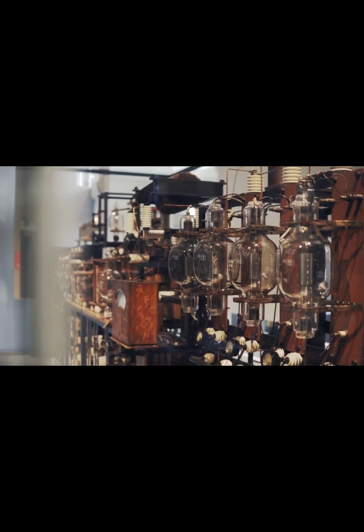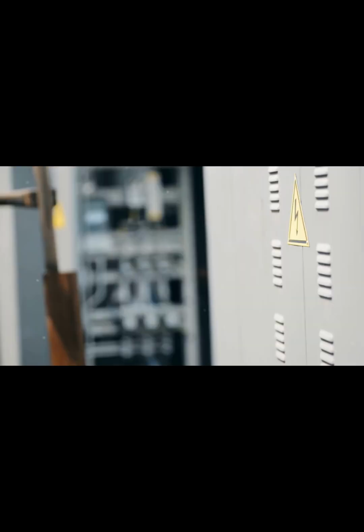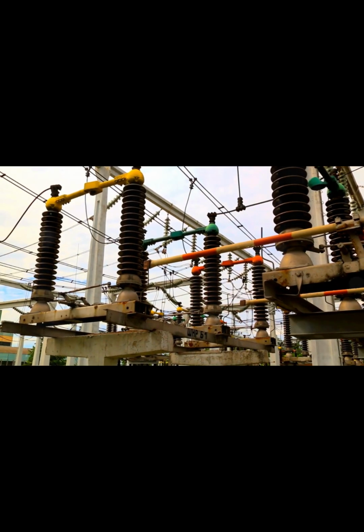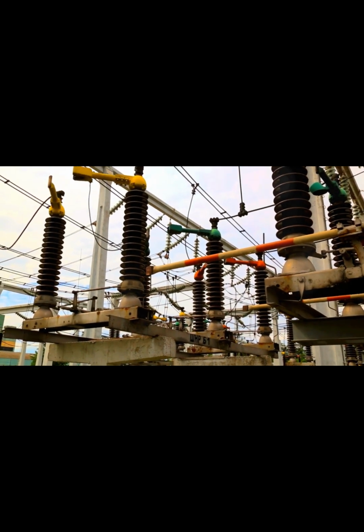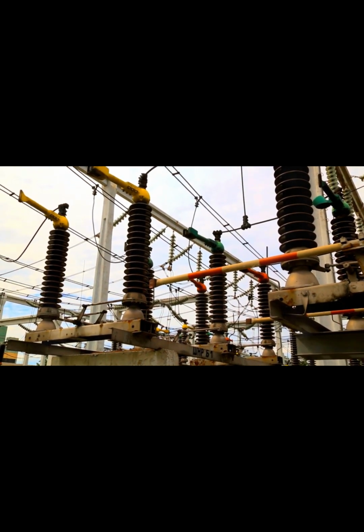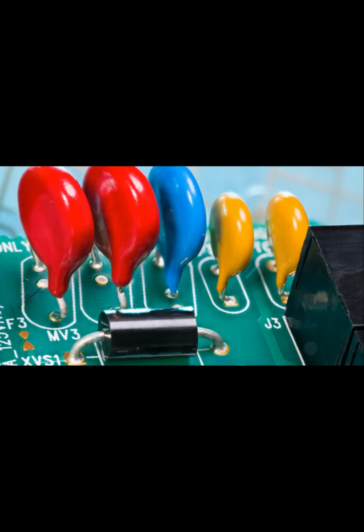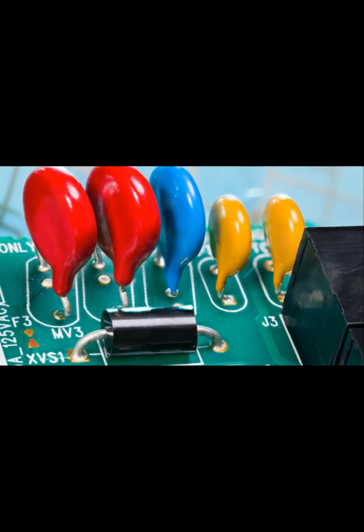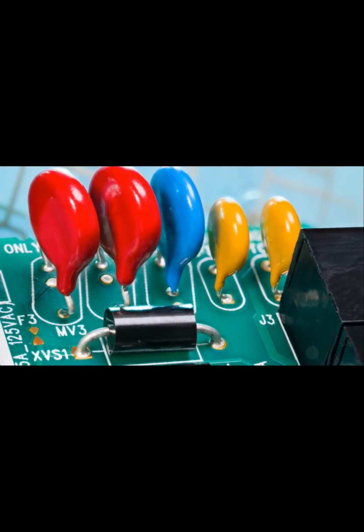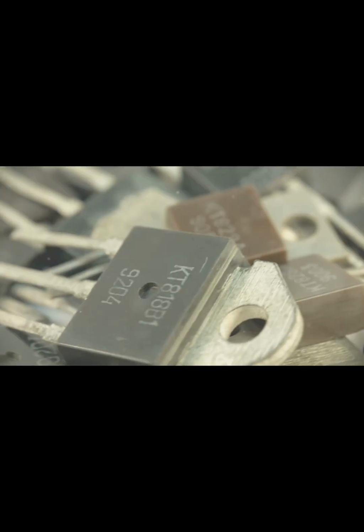This is a critical parameter that defines the maximum reverse voltage a diode can withstand before it starts conducting in the reverse direction. We can exploit that by intentionally designing circuits where the diode will only conduct in case of a voltage surge, diverting the excess current away from the delicate components. This way, diodes act as guardians, ensuring the longevity and reliability of electronic devices by preventing damage from unexpected voltage spikes.